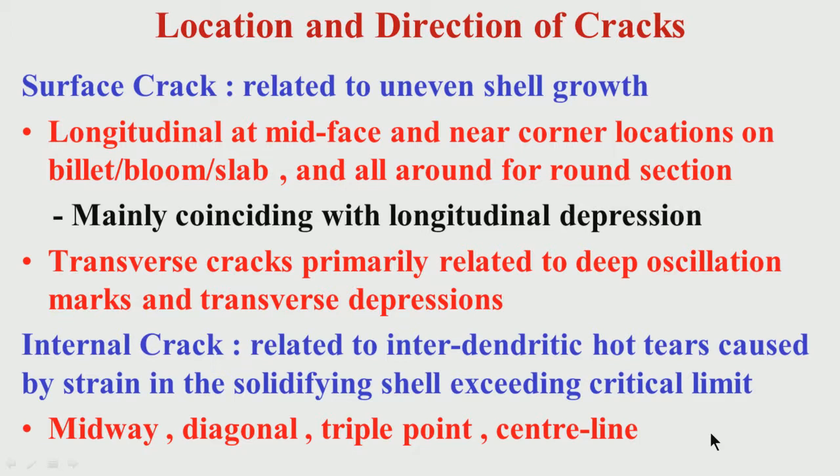If you have, as I have mentioned, an equiaxed zone at the center, you have less central crack and central segregation, because this is getting relatively distributed. But if you have a columnar zone extending to the center of the cast, why will the columnar zone extend?